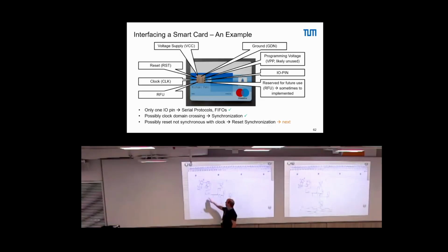So we know that from here to all the flip-flops internally, we have a specific time period, and only after this time period the reset happens. And if we have it synchronized here and then distributed the signal, that really helps against any metastability issues and so on. So only synchronization, not really, or only up to a certain extent.